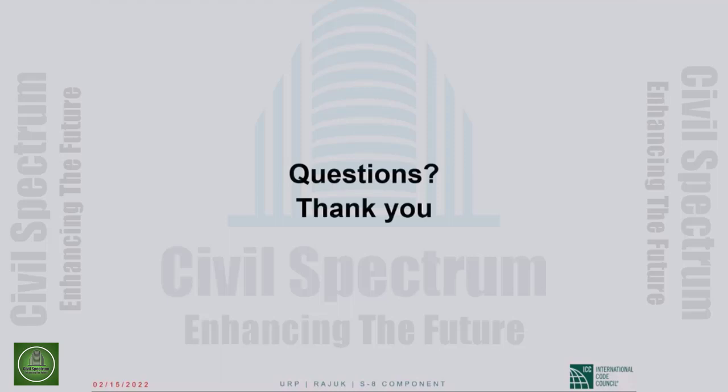When should we use the CQC, complete quadratic combination, and when SRSS? When the modal periods are close together, SRSS tends to give you inaccurate results. Then you switch to something like CQC. How close is close? There are guidances available in the literature. I cannot tell you without checking, but you can find that information. CQC will consider the correlation between different modes. So if you want to consider correlations, then CQC is the method to go.